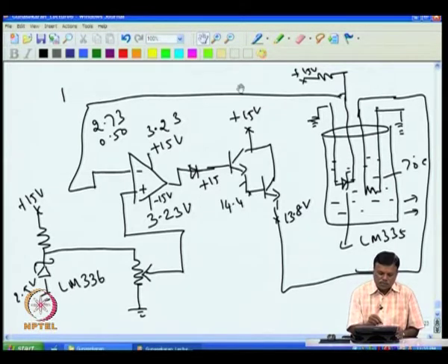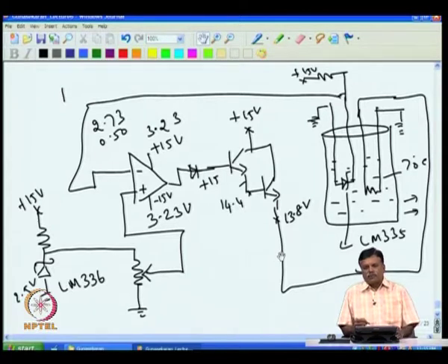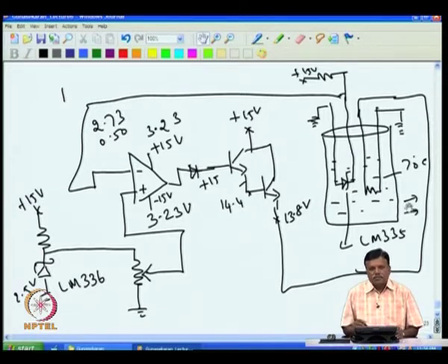Once the temperature goes above 3.23, again it will turn minus and it will go off. So, like that it will keep going on and off, and then maintain this around 70 degree C, not exactly 70 degree, it will be maintaining a little more than 70, and then it will come down a little below 70. Like that it will be doing, frequently switching on and off, and then maintaining this temperature. In fact, this is what we do in real life.